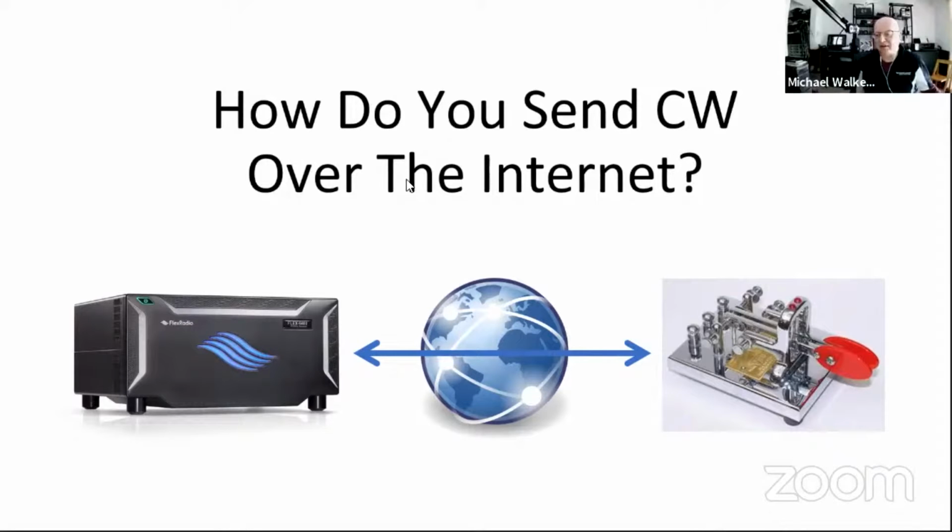Thanks, George. I actually wanted to mention RS-485. If you're worried about it or you think that's freaky, it's just RS-232, but it's long haul. It's a bit more to it than that, but in some ski racing stuff I've done, we've used RS-485 to go 7 kilometers. So instead of what the spec is in RS-232, George, 9 feet, something like that? Yeah. I think it is actually. It's like 3 meters. It's like 25 feet. They're 50 feet, yeah. So which it's only 2 wires, point, so.